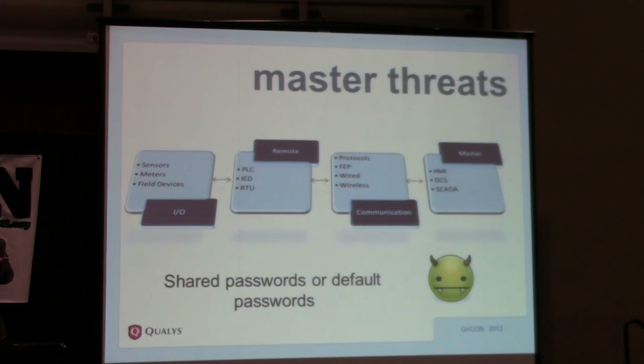Test if it still has the default password, because the password is already in the manual, it's on the internet, that this XYZ system from XYZ company comes with this default password. So I'll just try that password. So basic things like passwords and default passwords are still an issue when it comes to Scada systems. There is no password change policy either.